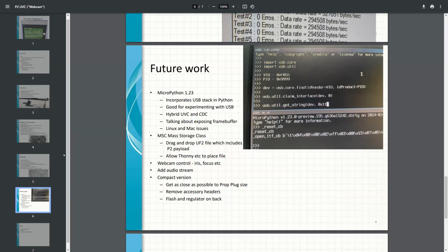When I thought about the smart pin, I thought it could generate an interrupt when there is new data from the USB, but it seems like I was getting too many interrupts. Oh yeah, I designed it. I should have made it work a little bit differently. I think it has an interrupt on change, but the trouble is, anytime anything transitions, that's a change. So you'd get way too many interrupts. So I just dedicated a cog. You could possibly make it run on interrupts, but when it's busy, it just hogs a lot of the time, because it has to do things.